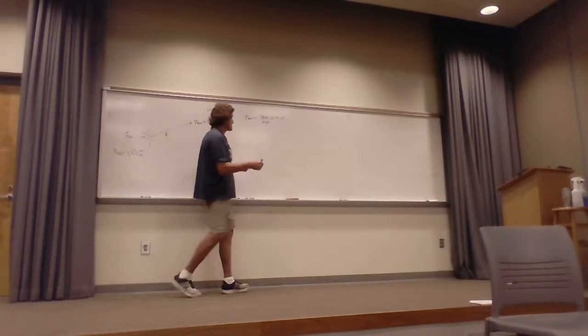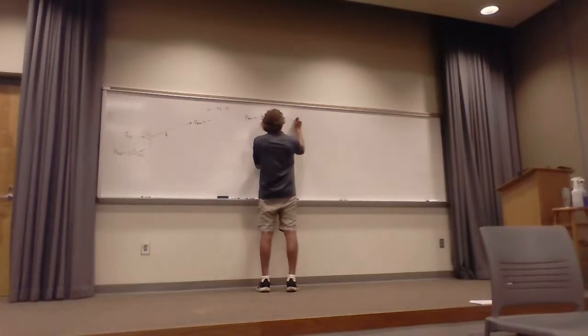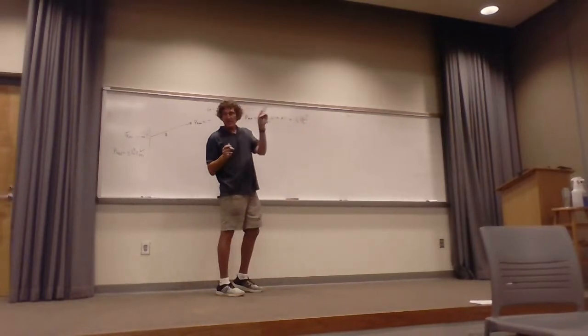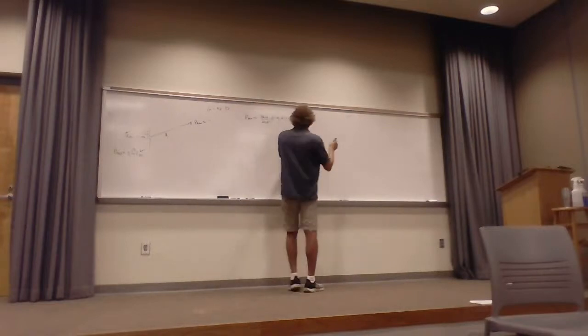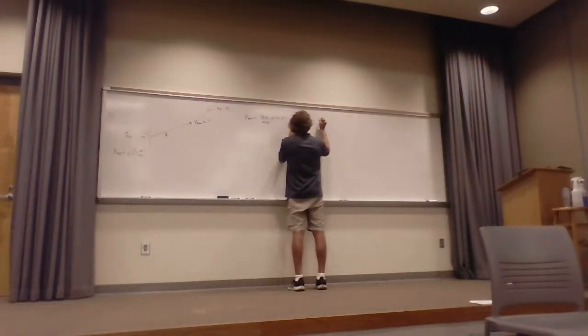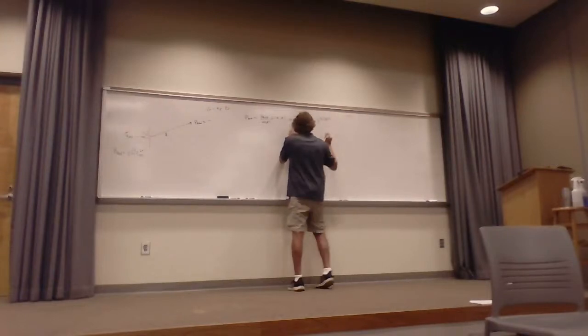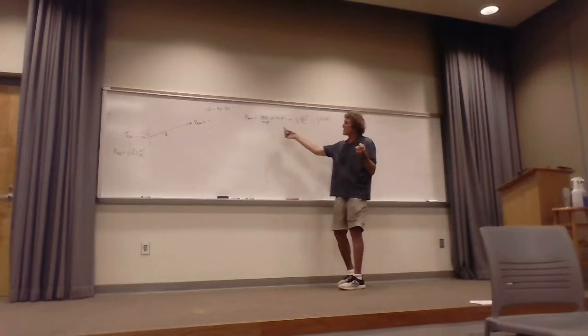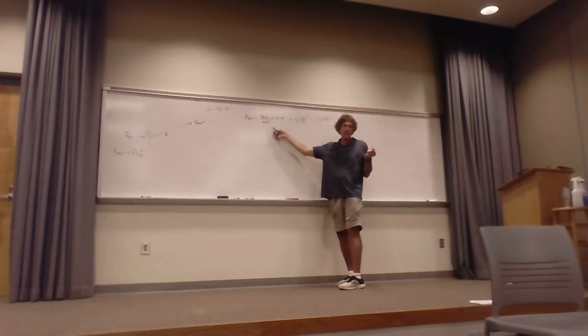That's also equal to 1/2 times the magnitude of the E field at that point squared, divided by eta naught, since this is propagating fields in the far field, in the radial direction. And it's also equal to 1/2 eta times the magnitude of the H field squared. So if you want E or H, and you have the power radiating and the gain, you got it. You tell me a distance r and you got it. You with me on that?